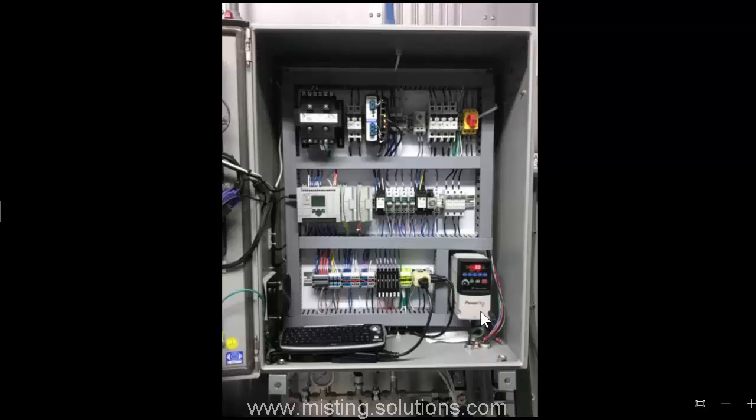And the last group we're talking about is fuses, and we did talk about these a little bit. It's these 6 right here. These are the solenoid coil fuses. 4 on the right are for the zone 1 through 4 zone, and the 2 that are on the left are for the input water supply and the bypass solenoid valve. And there is one other item similar to that, and that's the disconnect itself. It's a 3-phase disconnect rated at 25 amps.